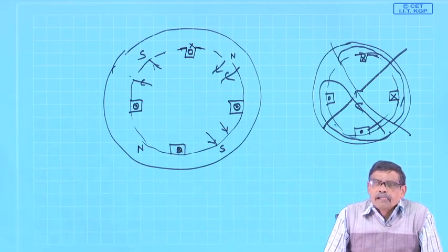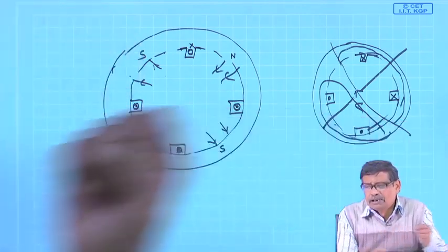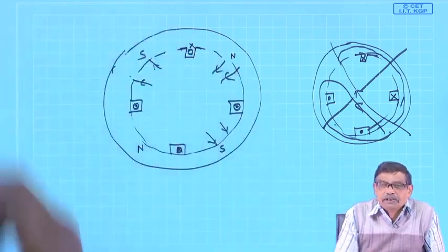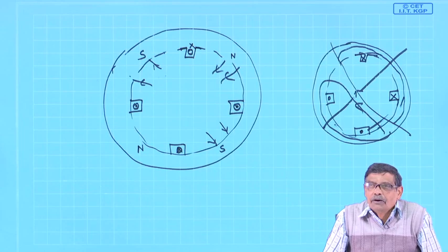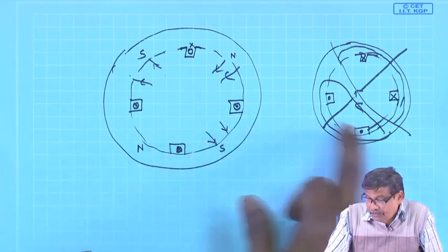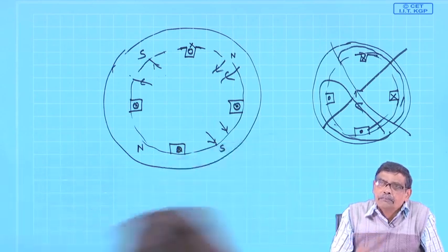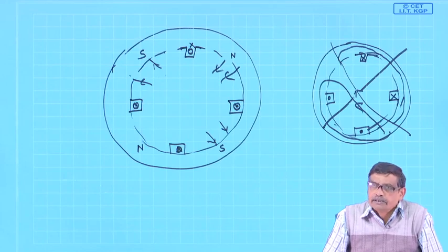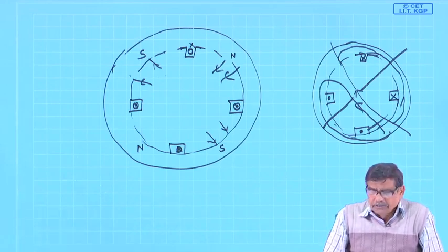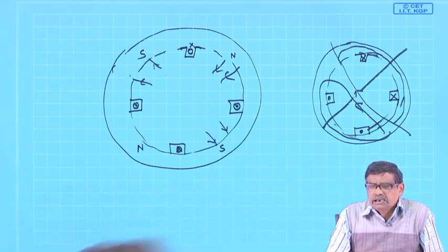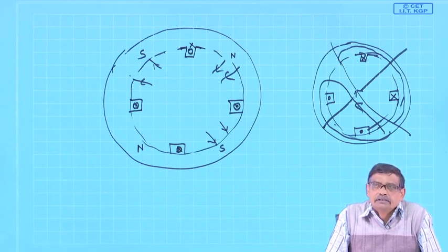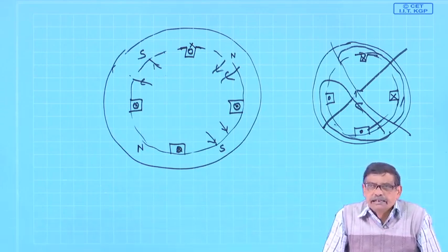But obviously, many terminals have to be brought out from the machine, not simply 2 terminals for R phase, 2 for Y phase or 2 for B phase. To carry out this kind of operation, you require many terminals brought out, maybe from the groups of a particular phase. So, it was cumbersome that way, and you have to change that interconnection only to get 2 levels of speeds, that is all, and having of course, a cage rotor.